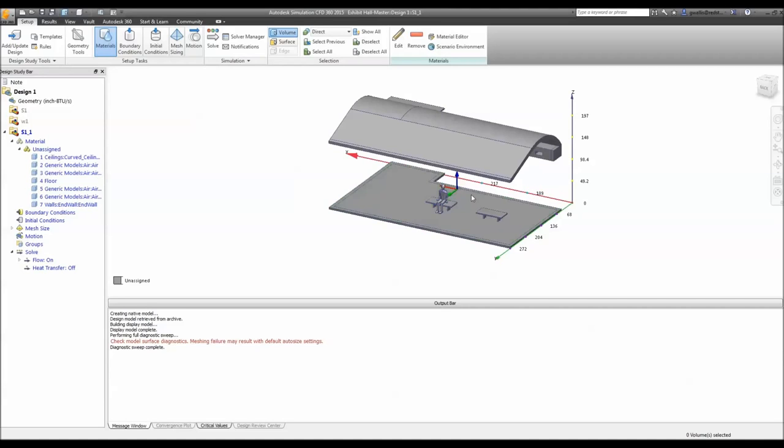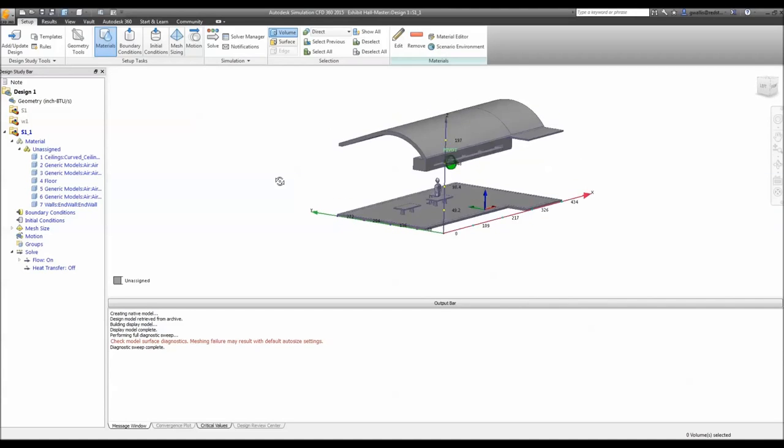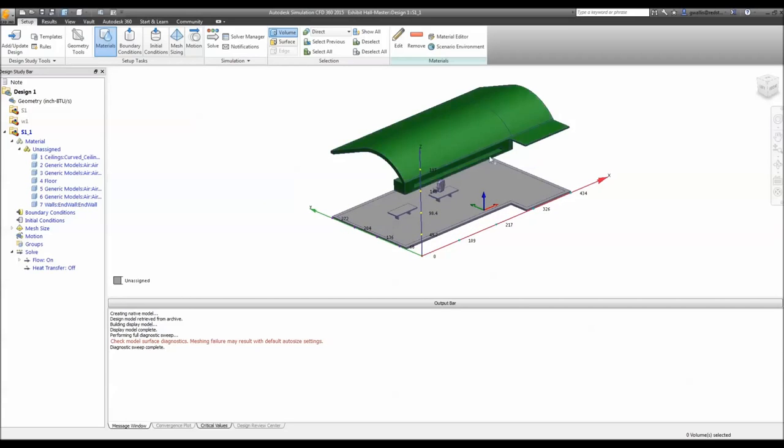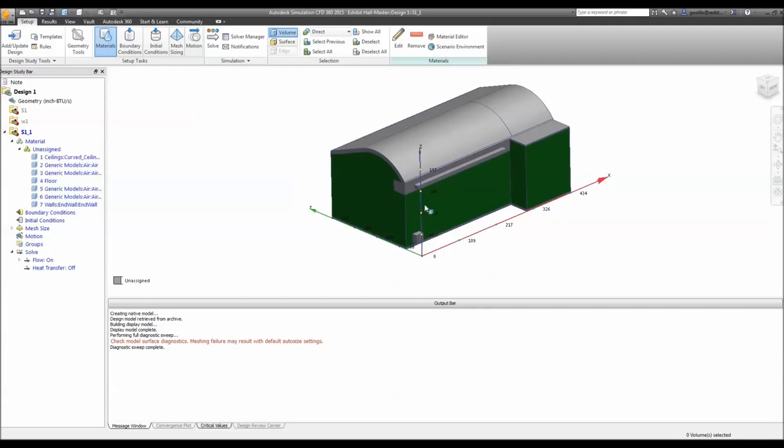So we're going to create the summer and winter scenario. Just one last thing, as you see me go through and set up the study, the back wall here is actually going to be adjoined to an existing wall. So when we set up our bounding conditions, you'll notice that we don't assign any specific heat thermal capacities and things like that to the back wall. So let's go ahead and start creating some of the boundary conditions.